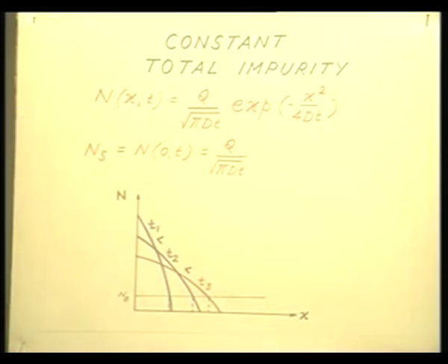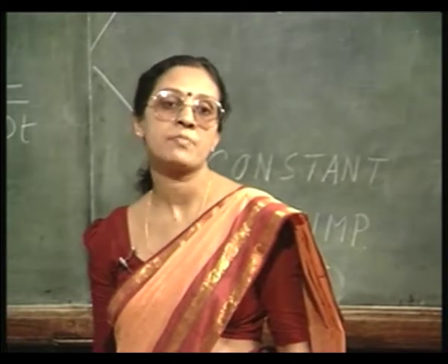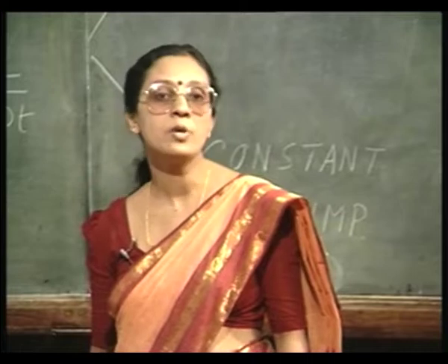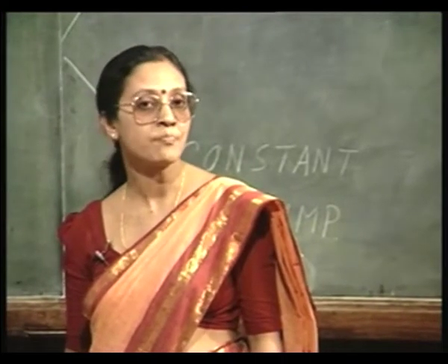As the drive-in progresses, if we carry out the drive-in for a longer time, t2 being greater than t1, then look at this violet curve, the surface concentration has come down. Carry out drive-in for even longer time, t3 greater than t2, and the surface concentration falls even below. So, as the duration of drive-in is increased, the surface concentration decreases and obviously the dopants move further and further inside the semiconductor.